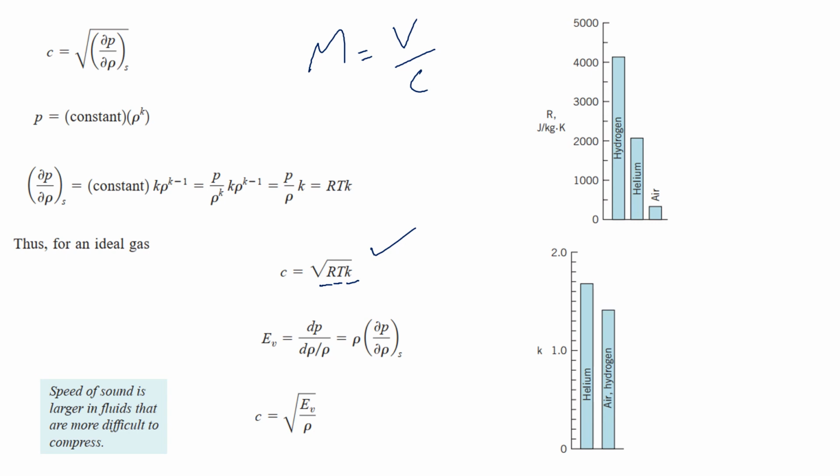Why? Because sound is a pressure pulse or a pressure wave, and the more the fluid around a certain object is compressed, it means that the object has a high velocity, and when that velocity exceeds the speed of sound, it sends shock waves into the compressed air. The pressure pulse generates a shock wave, and we hear a boom-like sound, and we say that now the Mach number of a certain aircraft or entity has exceeded 1. As long as the Mach number remains below 1, that is the safe regime for our air. And after this lecture, we are going to discuss different regimes based on the Mach number, and how the compressibility of the fluid is related to this dimensionless Mach number.